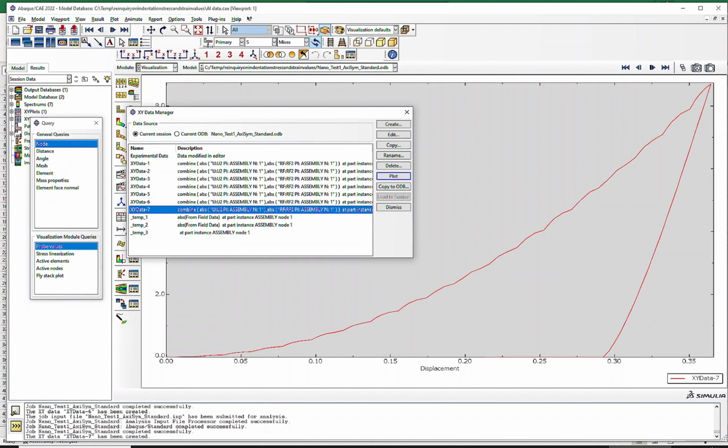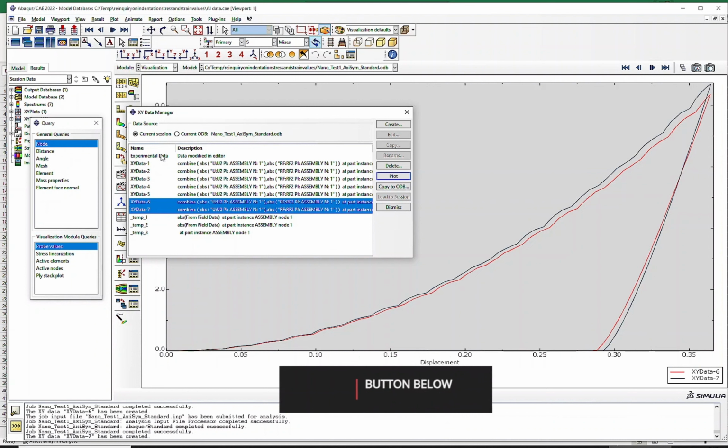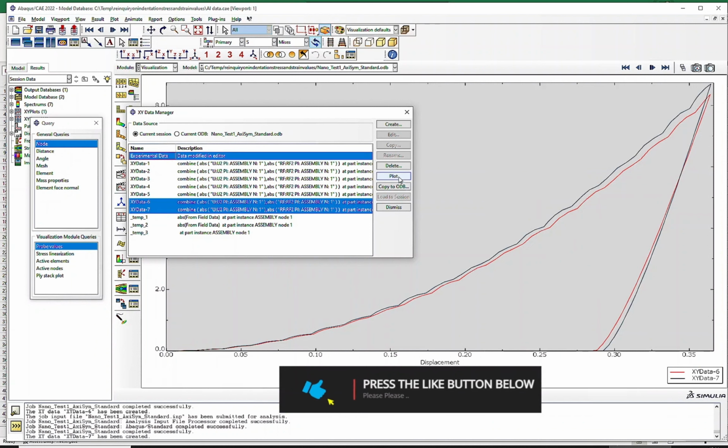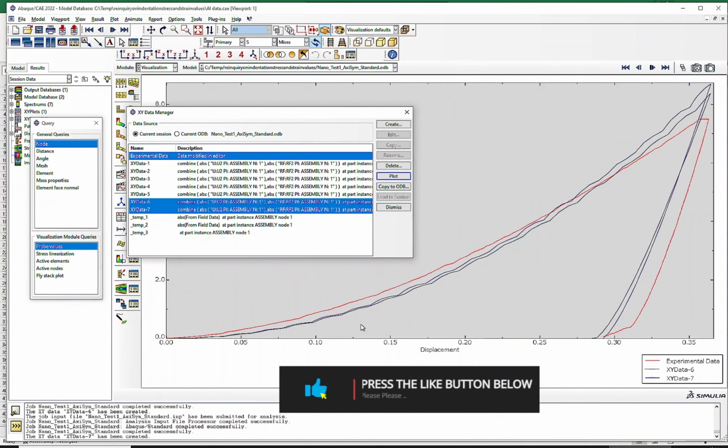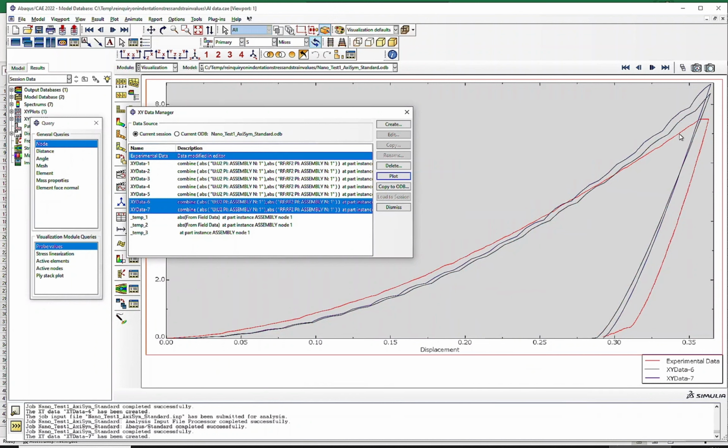And yep. So now what I'm going to do is compare this with the last plot to see if there is any difference. You see there's a significant difference. The 7 one is the most recent, and it has gone up slightly with the Young's modulus. It should be the case because we are increasing the stiffness. If I compare with the experimental value, you see it's much closer to the experimental value, although it's going up from here.